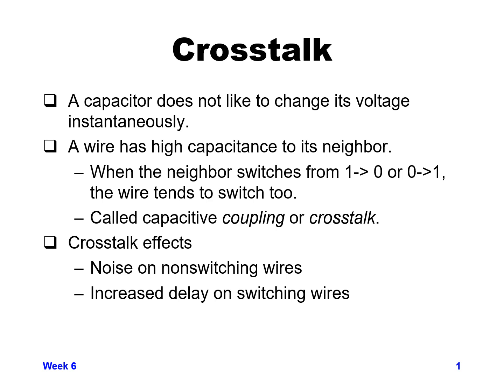that capacitance likes to keep the voltage delta between the two neighboring wires the same, because the voltage delta between the neighboring wires was 0 to begin with. They were both at a value of 1, so there's no voltage difference between the two wires. So as the one wire is going from 1 to 0, the neighboring wire also wants to get pulled from 1 to 0. So in effect, a wire that was supposed to stay at a constant value of 1 starts getting pulled down to 0. And this effect is called capacitive coupling or crosstalk.